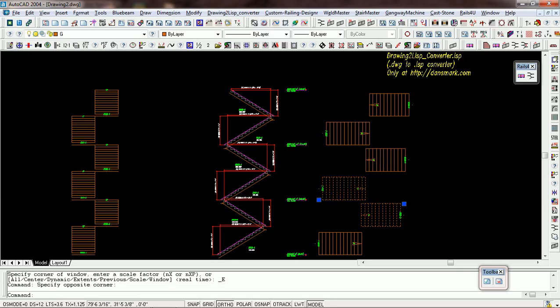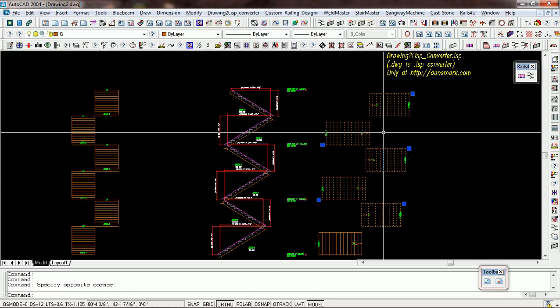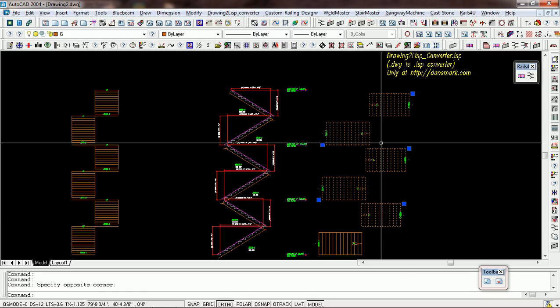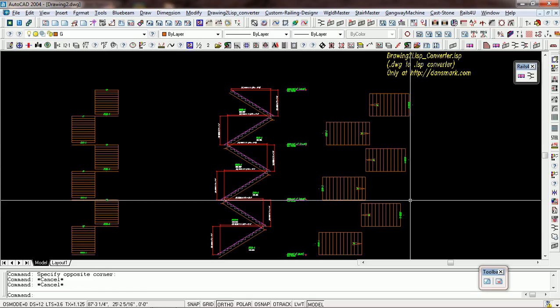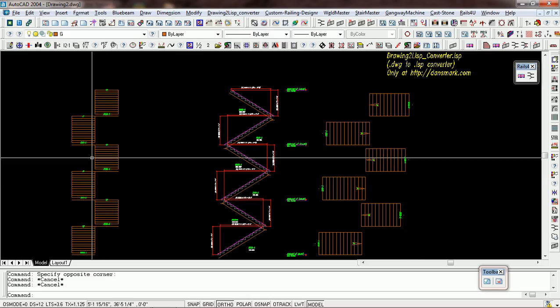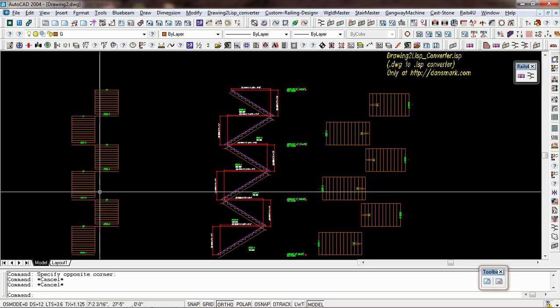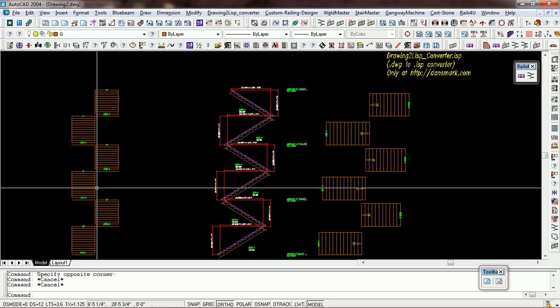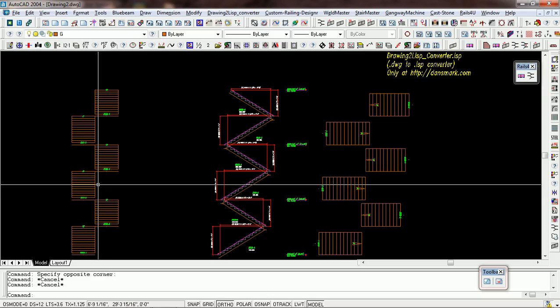You can move these plan views however far you need to away from each other, and line the tops and this, that, and the other, so that you get your plan views correct. And also your section view over here, you can move those so that the stair is correct in the width that it needs to be.